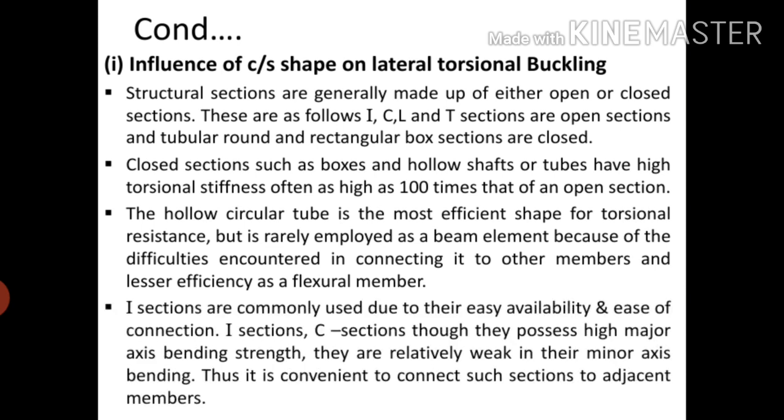And I sections are commonly used due to their easy availability and ease of connections. I sections and channel sections, though they possess high major axis bending strength, are relatively weak in their minor axis bending. Thus, it is convenient to connect such sections to adjacent members.